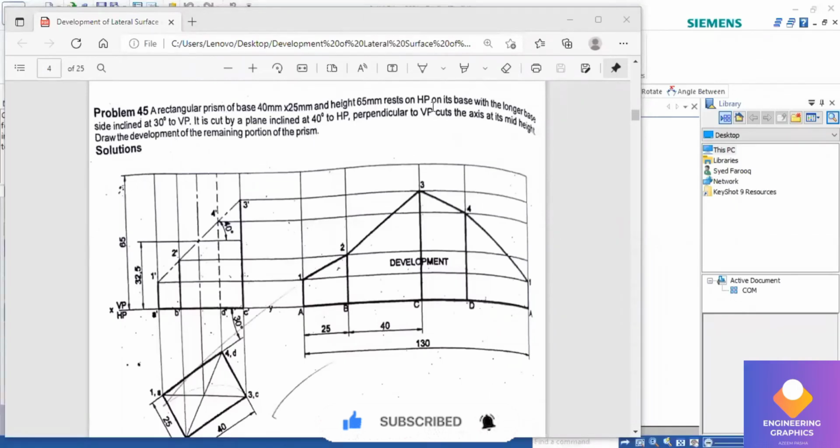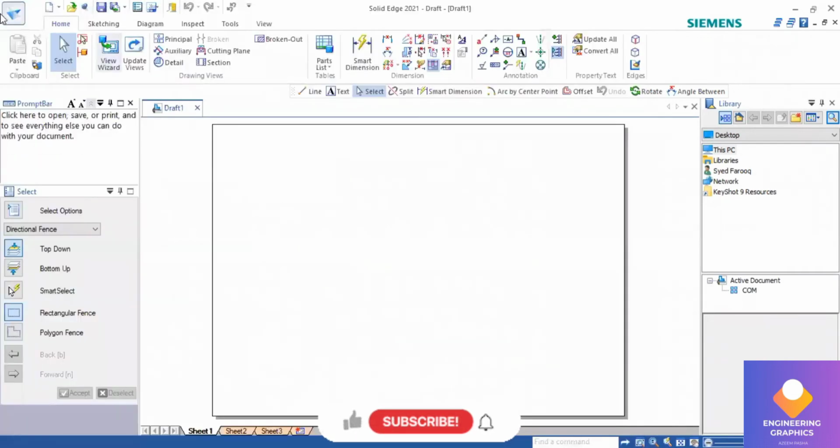You have to draw the development of this rectangular prism. You can see here it has dimensions 40 into 25, and axis height 65. It is resting with the longer side at an angle of 30 degrees, so you have to draw a 30 degree angle line, and then place this rectangle, and here the axis is given as 65.